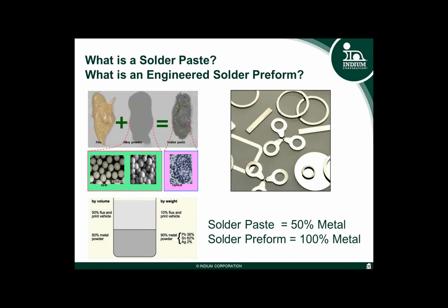Positives, it's great for mass manufacture and application. Potentially negatives in some applications. Flux residues are not required in the application, or a flux residue would actually contaminate the surface of a component in play, such as a die surface or hermeticity of a seal, for instance, and maybe even blocking out the function of that device.